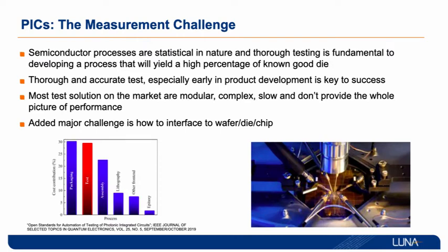When you look at the measurement challenge for photonic integrated circuits, it's really pretty daunting. You have all of the complexities associated with optical test in general for high-speed devices, of which there are many. And then you add to that the complexities of getting light in and out of these incredibly tiny devices that are embedded in a chip or a wafer and in a material with a significant index contrast to glass and in a planar geometry that does not match fiber optics.